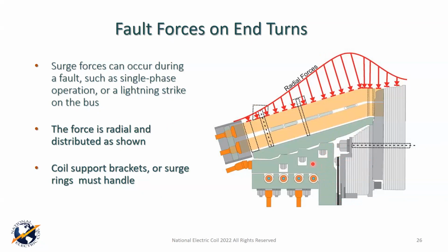Okay. Now, Franco asked a question about resonance. Can it be the consequence of vibration? Vibration could mean pulsing operation. Well, in layman's terms, the relationship of vibration and resonance is that resonance can exhibit itself in exceptionally high vibration, but vibration does not create resonance. Resonance is created by the natural frequency of the device.